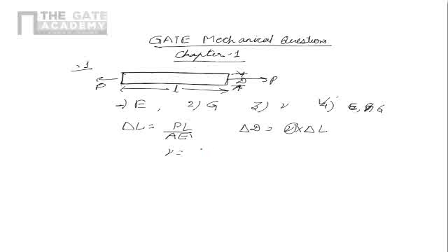Two times 1 plus nu is the ratio of E upon G. So if we know both E and G, we can figure out the value of nu from this equation, and from that we can calculate the value of delta D. So that answer is option D, the fourth option, which is both Young's modulus and shear modulus. Now question number 2 and 3 are linked questions.